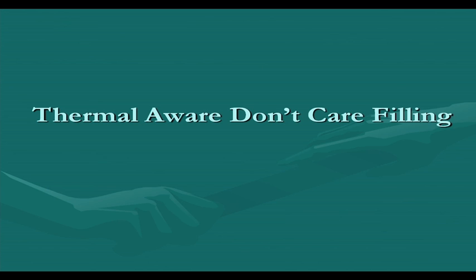Next, we look into another way of minimizing temperature during testing, via don't care filling. We already know that don't care filling can be utilized for power minimization, but it can also contribute to temperature minimization. But one thing we must keep in mind is that we cannot go for scan based minimization and all that, because that is the weighted transition metric based power minimization. That does not have any effect here, because we need to simulate the circuit, as it is very much dependent on the floor plan.